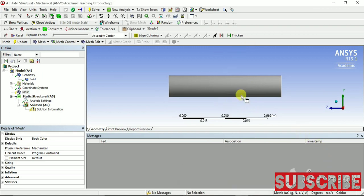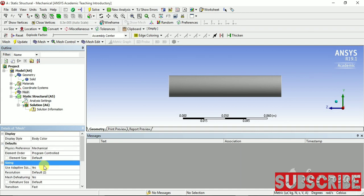The mesh tool creates a mesh of polygons, quadrilaterals or triangles, in order to increase the accuracy of the result or the simulation in a finite element analysis. Now, in the mesh there are different things that are present. The first thing is the sizing, the element size. In this you can define the particular size which you want.